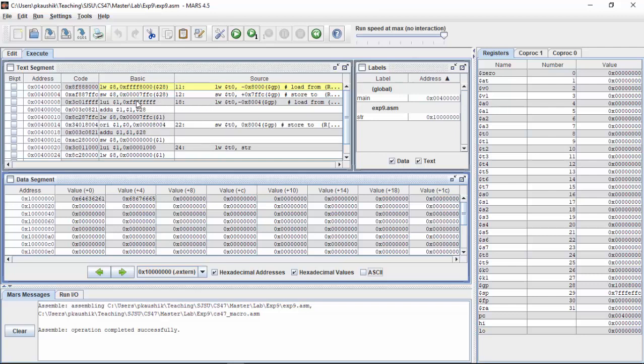It involves a lui, and then an add: you load upper immediate into the $at register, and then you add the content of the $28 register onto it, and then you use $at as your base address with some offset.